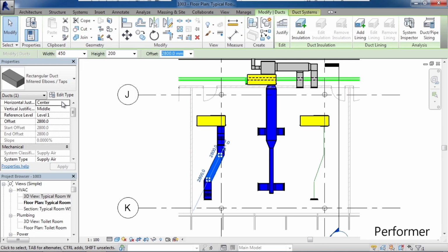So these are just some of the areas pointing out the differences between a placeholder duct and also a regular duct. So as a review, in this lesson, we looked at duct placeholders. We discussed what the difference is between a duct placeholder and a regular duct. We also looked at where to place these duct placeholders from, the Systems tab and the HVAC panel.